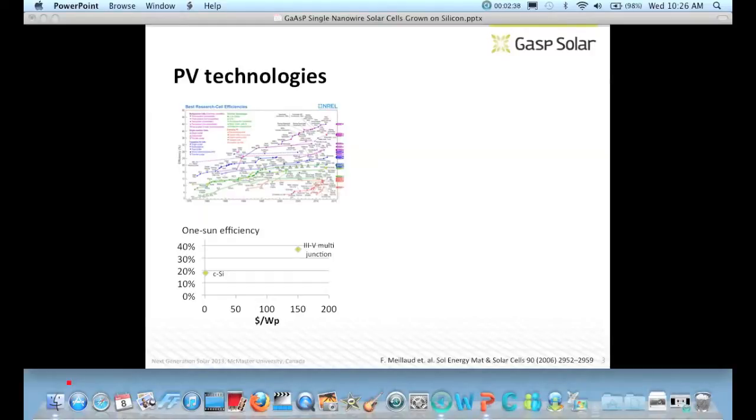You could also plot the cost on the Y scale here. You have the cheap, inefficient plastic solar cells, at close to zero cost, and the cost then increases as you go up until you get to the silicon and the III-V. Looking at dollars per watt peak, these are just some rough production numbers. As we just learned, the cost of making a monocrystalline solar cell at production scale is close to nothing, below $1 per watt peak. You don't earn any money on it. The typical production efficiency for SunPower is slightly above 20%, and for the Chinese cells slightly below.